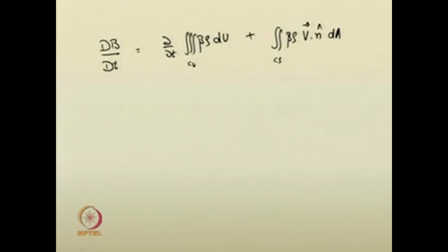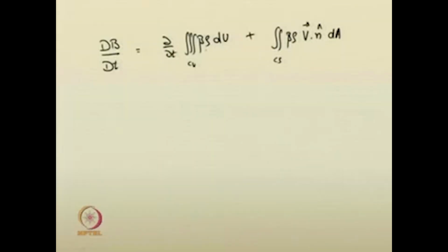We had discussed all the terminologies of these equations earlier, and as we suggested, the flow is predominantly one dimensional, so we are just going to consider only the momentum. You know that the net change of momentum with respect to time is equal to the net force acting in the control volume. This quantity was given as sigma F x, and if you recall, the net forces acting on the control volume were pressure forces on the left side, pressure forces on the right side, the component of gravity